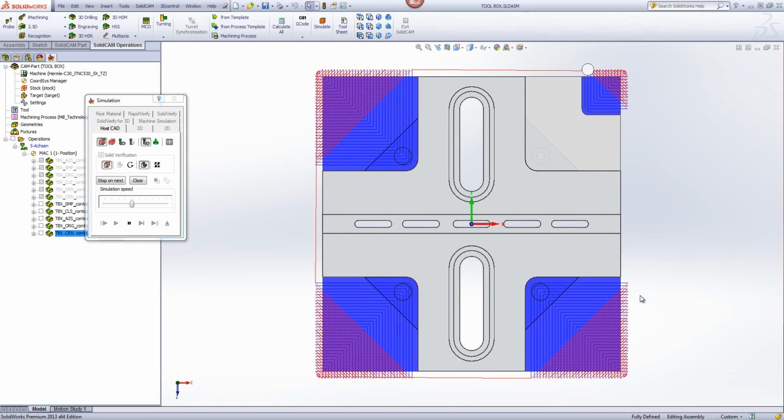It does not work out in these areas because in a profile operation, if you do a clear offset, it takes the entire wall and just pushes it out. So you'll end up working these areas with this size of a toolpath out here as well. This is actually saving you time, it just cuts only where it has to work.